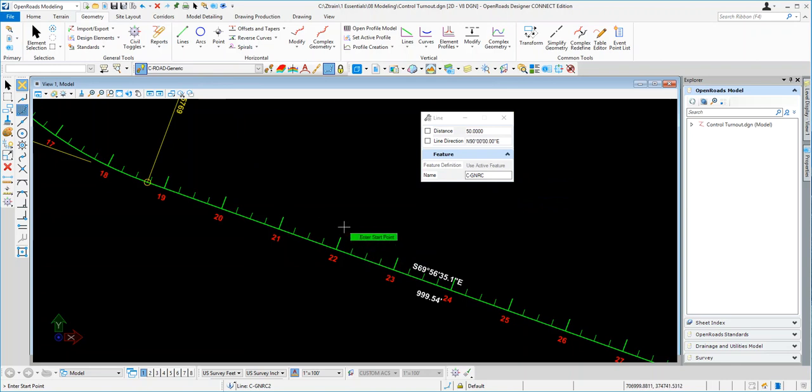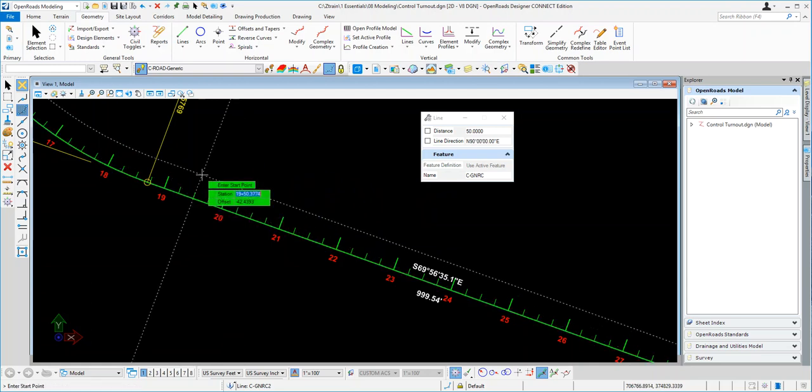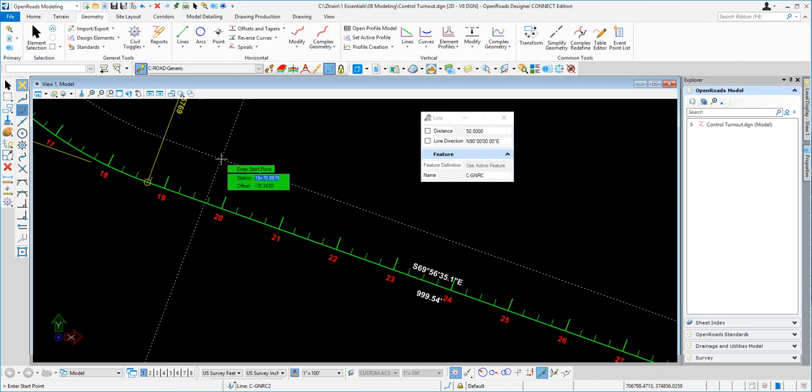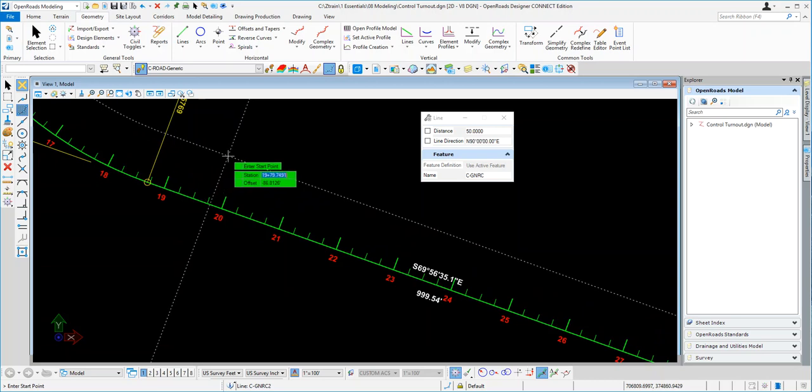Now I'm going to use Civil AccuDraw to lay this out because I want it to be relative to the stationing here along the main line. So I'm going to turn my Civil AccuDraw on and use the station offset option here. You'll see that it's added into the heads up prompts. Okay, using Civil AccuDraw, you're going to set the origin. So I'm going to hit the O key and tap the center line here on the main line. So everything now on the Civil AccuDraw is relative to that.